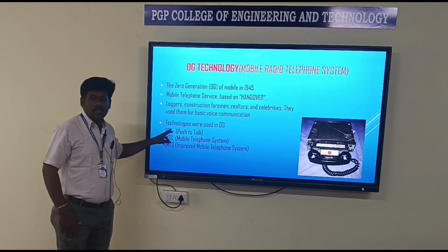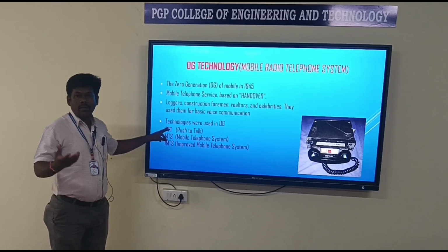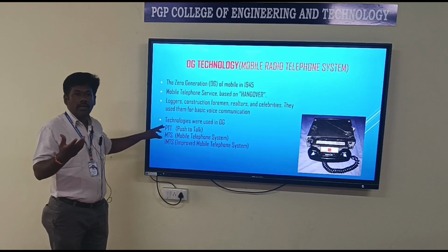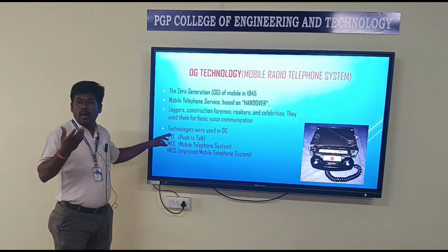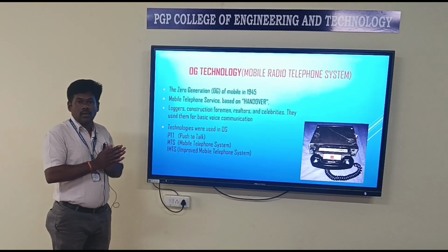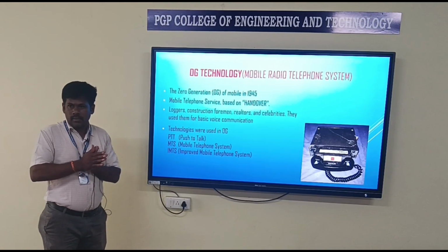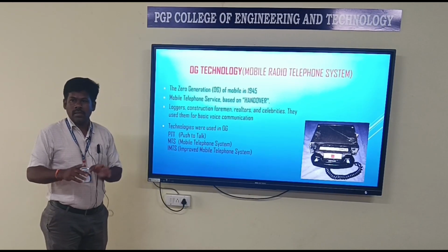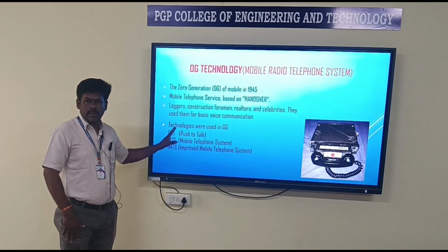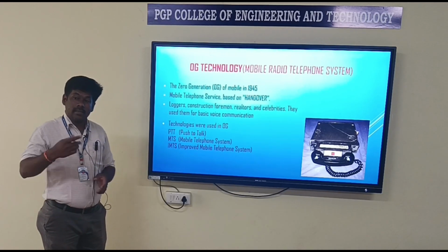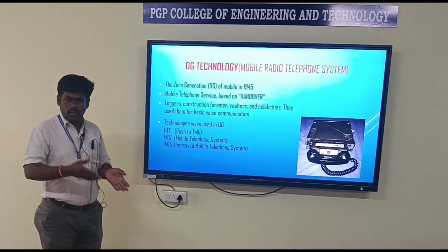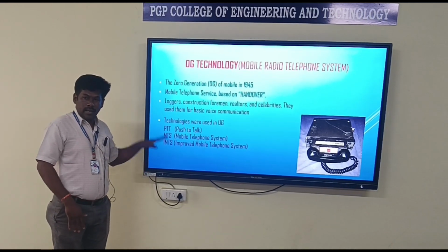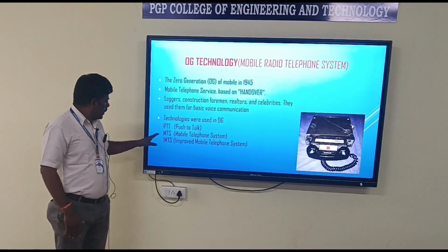So it is a half duplex method. The conversation happens half duplex. You have to know what is meant by half duplex and full duplex. Half duplex means at a time you can either talk or listen. Full duplex means at a time you can listen and talk. Nowadays mobile phones listen and talk simultaneously. So that is PTT.